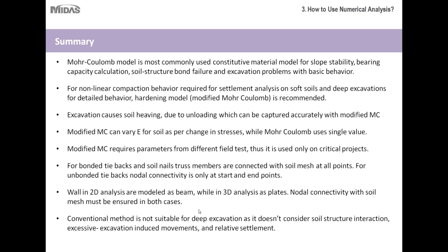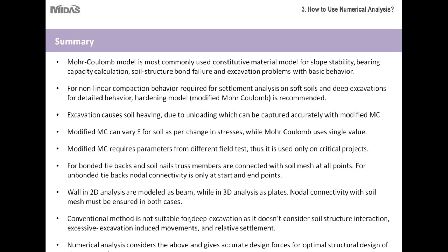That's very important. The conventional method is not suitable for deep excavations as it doesn't consider soil structure interaction, excessive excavation-induced movements, and relative settlement. And the numerical analysis considers the above and gives accurate design forces for optimal structural strength of shoring members. So once again, that's one of the key things to remember from this presentation: the strengths of numerical analysis over certain project types, particularly larger scale projects.